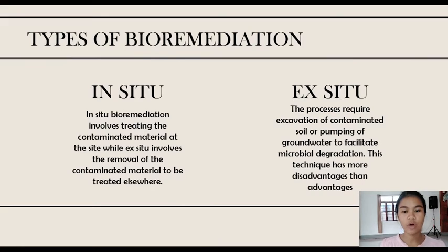Hello everyone, we will move on to the types of bioremediation. We have two, the in situ and the ex situ. From the word itself, when we say in situ, it involves treating the contaminated material at the site. While ex situ requires excavation of contaminated soil or pumping of groundwater to facilitate microbial degradation.